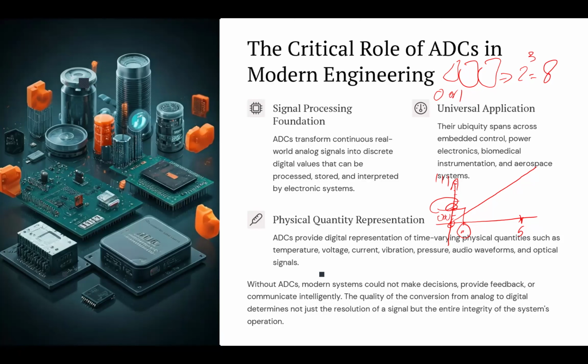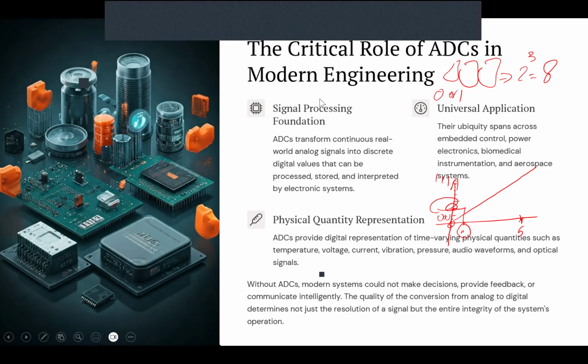We are going to go deeper to talk about what static testing is, but just to introduce, static testing is the testing of the ADC with a DC signal or a slowly varying signal, and we are going to see how the ADC would behave if the input is such a slow or constant voltage. So this is what we care about, and the critical role of ADCs in system